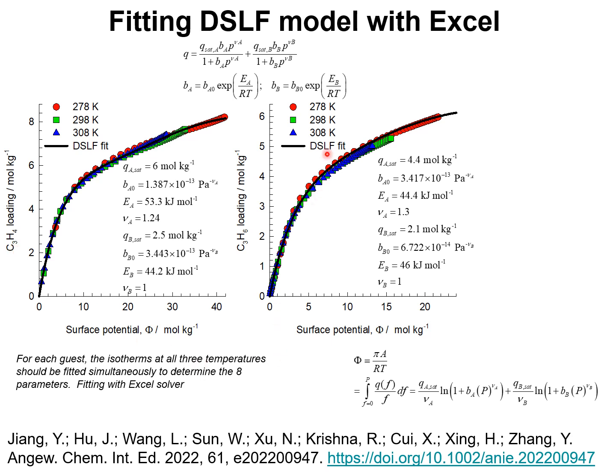A further advantage of fitting the DSLF model with temperature dependent parameters is that the isosteric heat of adsorption can be determined by analytic differentiation of the isotherm parameter fits with temperature dependent BA and BB parameters, as we shall see in the subsequent slide.